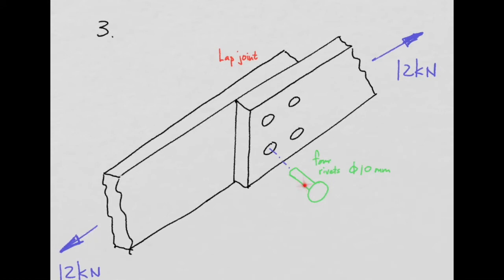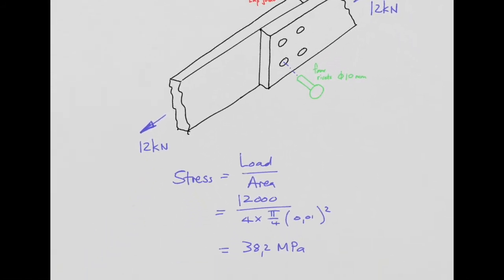And then a rivet is inserted in each of the holes and it protrudes out the other side. And then they would beat the end of that rivet over, hence holding these two plates together. Now if you look back at your notes and you look at single shear and double shear, this is clearly a case of single shear, because only on the surface where these two plates touch will there be a shearing action of the rivets. So the calculation is as before.